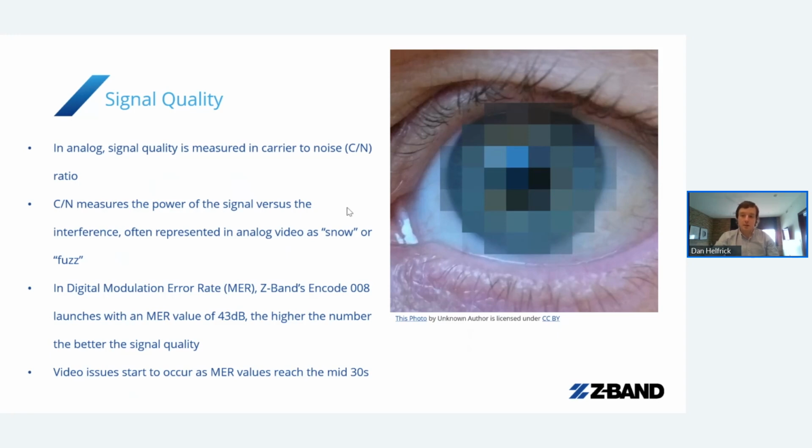This one's not as simple as tuning a value on an amplifier or throwing an attenuator in to fix things. I mean, maybe if you get lucky, it can be, but a lot of times if you have MER issues, we're looking at actual equipment replacement, which can be problematic and potentially expensive. And in the world that we live in now, it might take you 8 weeks to get that piece of equipment. Who knows, right? I'm sure everybody on the call had to deal with that over the course of the last couple of years.